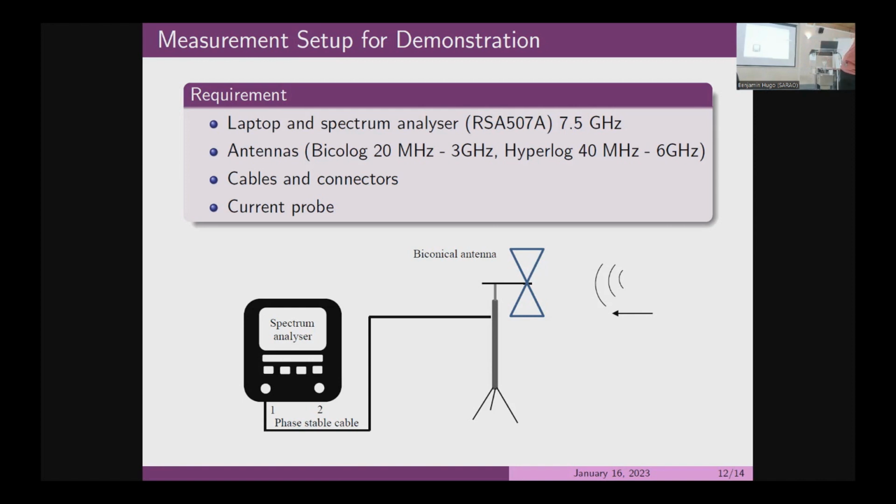The spectrum analyzer, as I said, is like a receiver. So it also works based on heterodyne technology. You do the down conversion of the signal, and then it's easier for you to analyze. But we also have the aspect of up conversion of the signal, because you might ask, where is the other term?